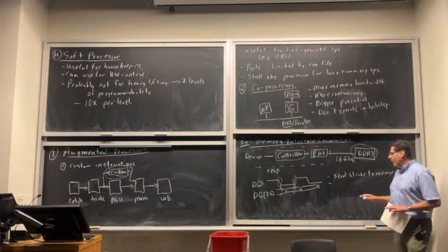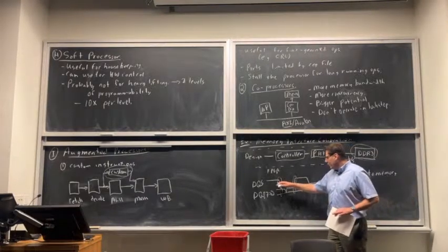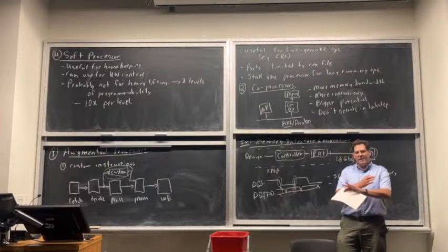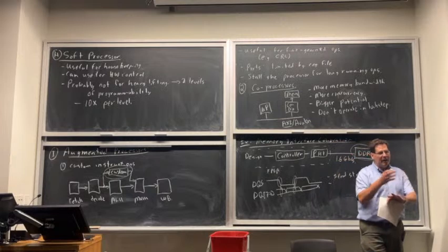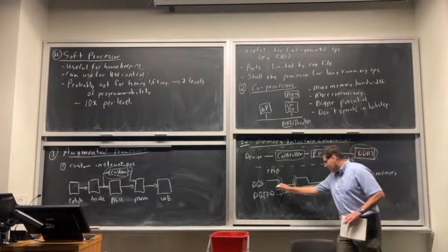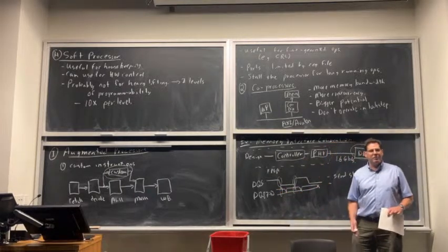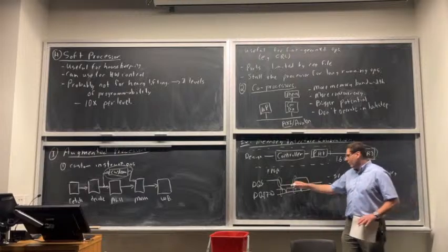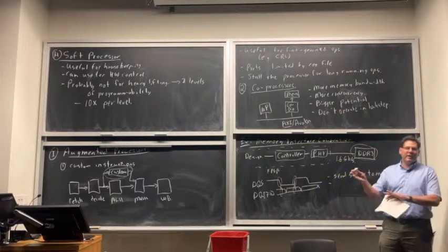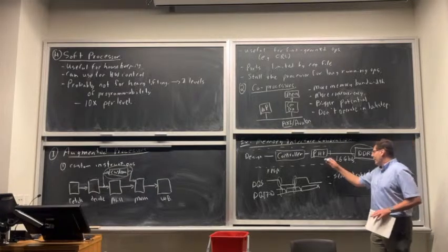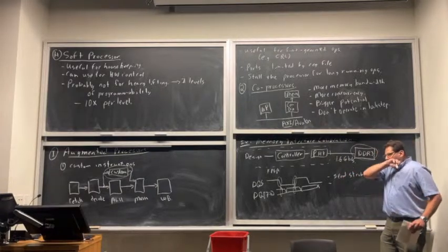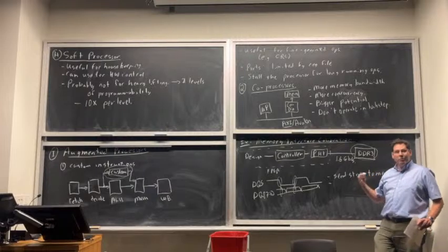So you basically have to adjust the edge of DQS and all of the delays on the DQs, like every single one of these 8. And then when you look at all 64, you got to do it across all 64 and all 8 strobes. Basically, you got to shift all their delays, okay? If you don't shift their delays around to account for all these mismatches, this will not work at this speed, okay?